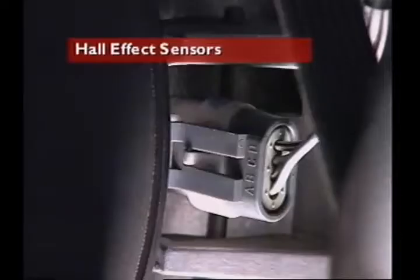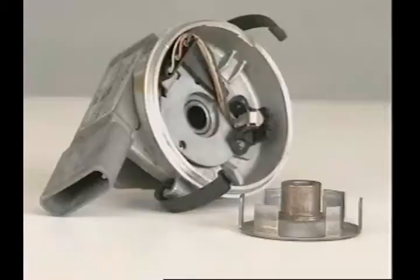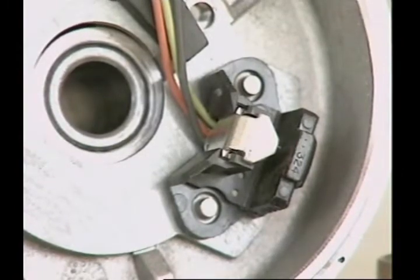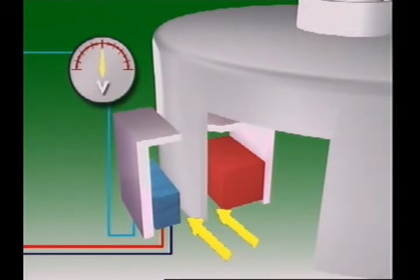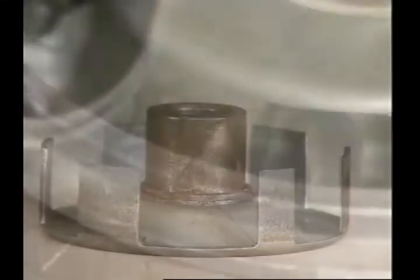Hall effect sensors can also provide a voltage signal and, like the inductive type, can be mounted on the crankcase wall or inside the housing of the distributor. The sensor has a permanent magnet and a Hall switch as part of its assembly and an air gap between the magnet's north and south poles. The switch is on one pole of the magnet, and an interrupter ring with a number of square-shaped blades or segments rotates through the gap formed by the poles.